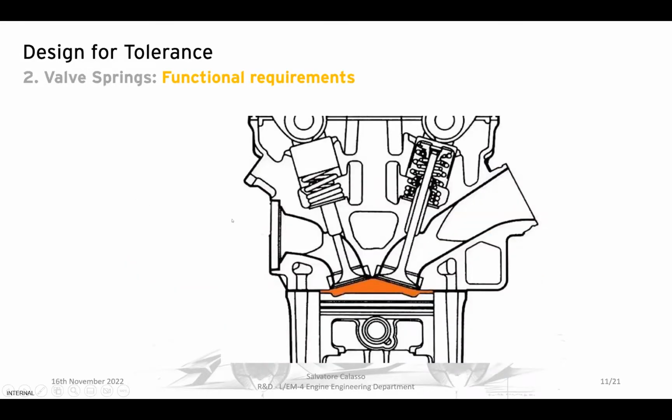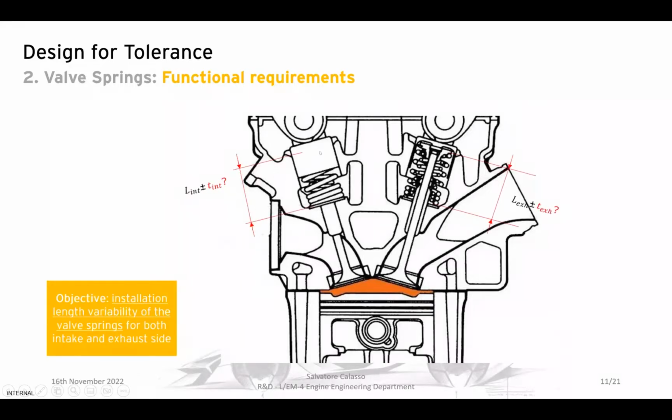The second case was related to the valve spring length. Our goal is to understand which was the length variability, because our goal is to understand the impact of the length variation on the component itself, because changing the length in installation of the valve spring means also modify the stresses on the components themselves.